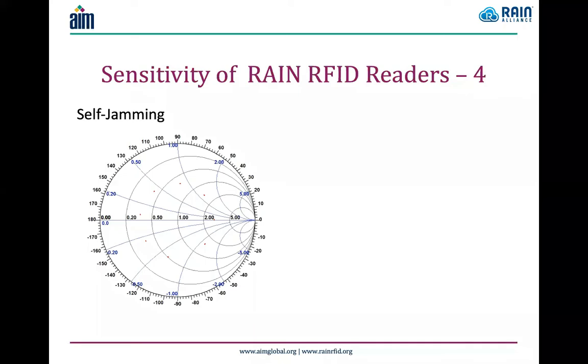Finally, let us just look into the Smith chart. Ideally, the impedance needs to be perfectly matched and is indicated here with the green dot at 0.0. In reality, it is not. The impedance of the antenna starts falling away from the center point. Here, in this particular example, it is indicated by the yellow dot. In addition, we also have other variations of the phase shifting that result in variation in the return loss calculations, which is dependent on the phase.